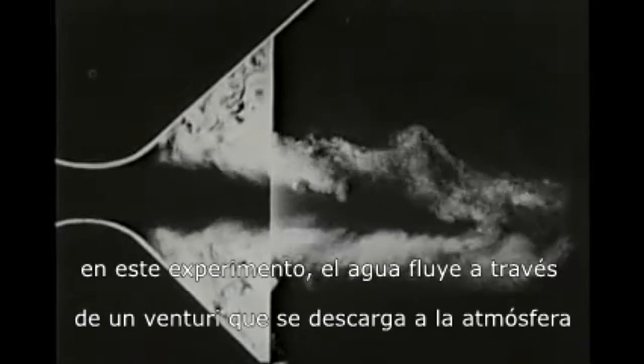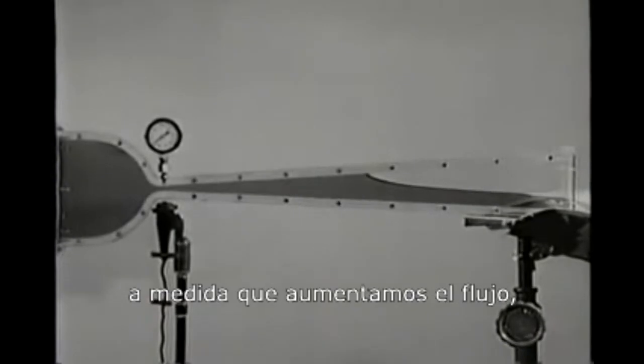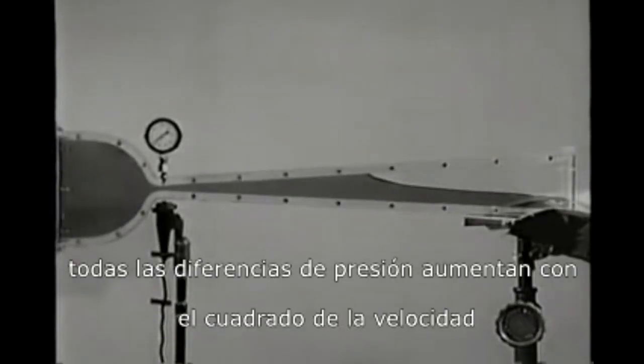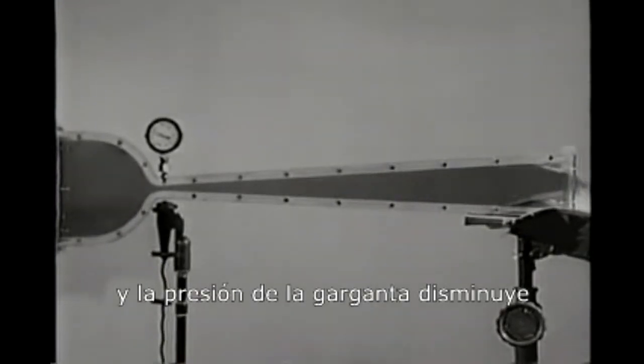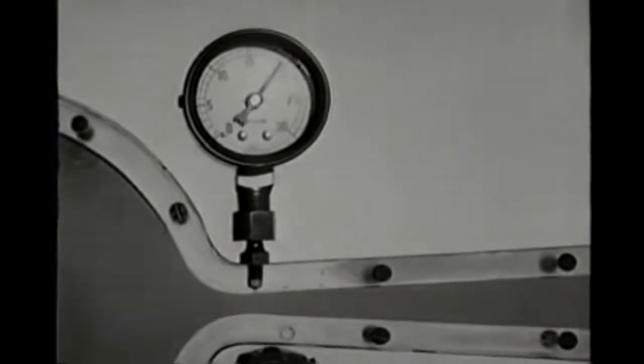In this experiment, water flows through a venturi that discharges to atmosphere. As we increase the flow, all pressure differences increase with the square of the velocity, and the pressure at the throat decreases. The gauge shows vacuum, and the pressure at the throat is now about 20 inches of mercury below atmospheric. Watch the throat.